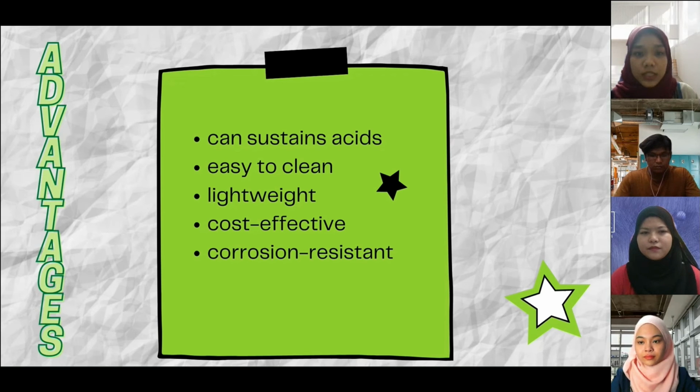It's also easy to clean because the glass-lined steel has been adapted to CGMP requirements for cleaning, cleanliness and sterilization. Due to its transparency and its high degree of surface smoothness, it is easy to clean using non-corrosive, low-pressure cleaning system. The surface of glass-lined steel also resists the build-up of sticky products, which means less frequent cleaning.